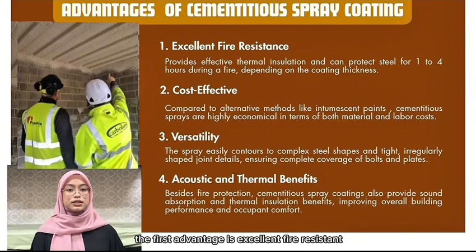The first advantage is excellent fire resistance. Cementitious spray coating provides effective thermal insulation, allowing steel structures to maintain their strength for 1 to 4 hours during a fire, depending on the coating thickness.